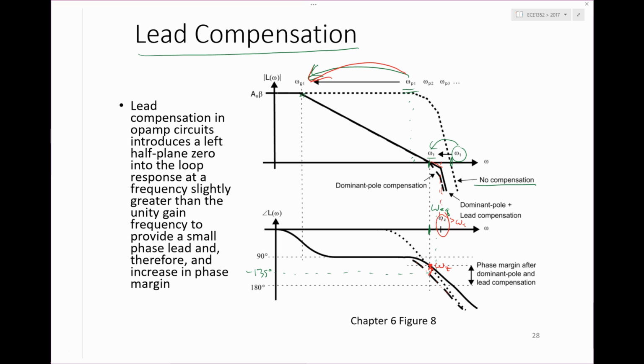That's the approach for all the cases we're going to talk about. The only thing that differs from one amplifier to another is, basically, where do we put the cap, and how do we stick in the zero? Usually it'll amount to sticking a resistor in series with a capacitor to introduce a zero. So that's what we'll talk about.